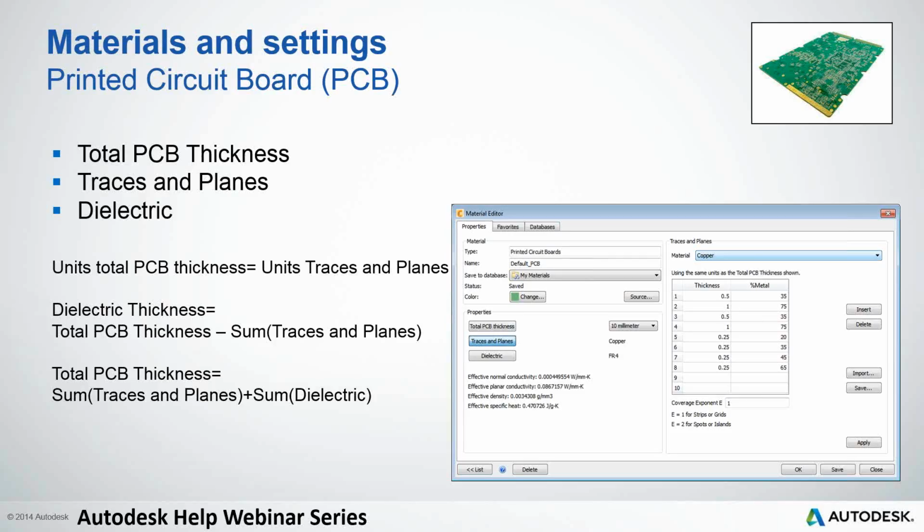Now, as you change these components, over on the left, your effective normal conductivity, effective planar conductivity, density, and specific heat are all going to change. And basically, you can play with these settings and edit what you need to in order to get overall accurate characteristics.